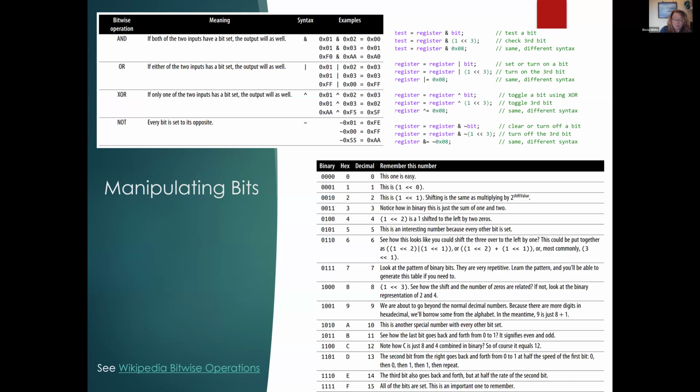There are lots of good C books out there, and there'll be example code for your processor. And if you've used C++, even then, you may not have worked much with bit manipulation, which is shown here on the slide. You need to remember all about binary numbers, and then bitwise operations. These are like logical and, or, and not. But instead of working on the whole variable, they work on bits inside the variable. I've been showing those with the register change on the previous slide.